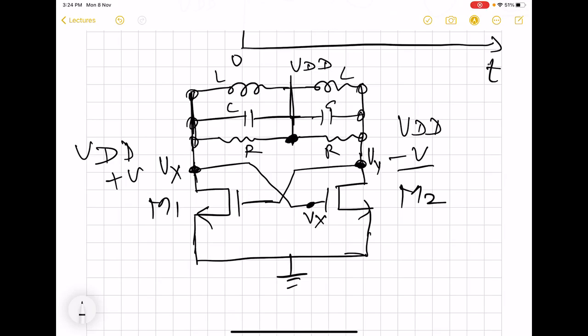So even if we remove this interconnect, there will be no DC flowing through these two resistors, because both ends are still at VDD. There is no DC current through any of these resistors, even when the explicit VDD is removed from the center, the common point of the resistors. And for AC, this point will continue to remain ground, because Vx and Vy continue to be of the same magnitude and opposite phase. So there is no need to connect DC to this common point.